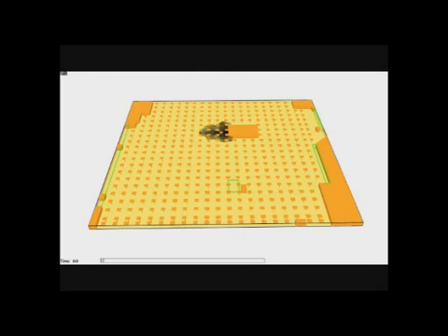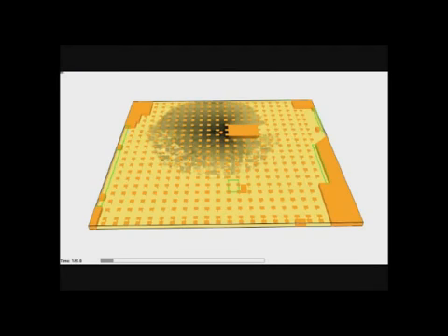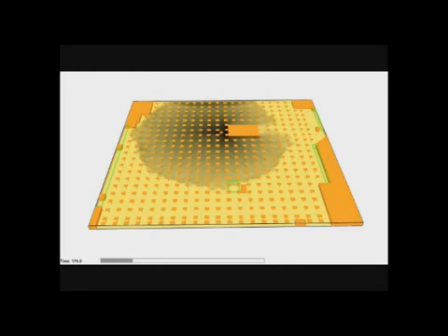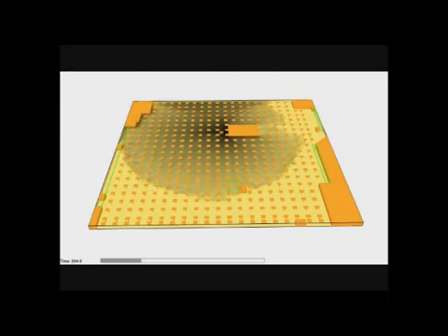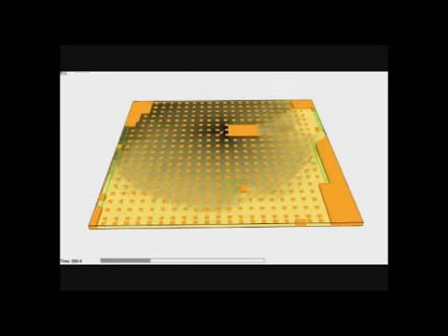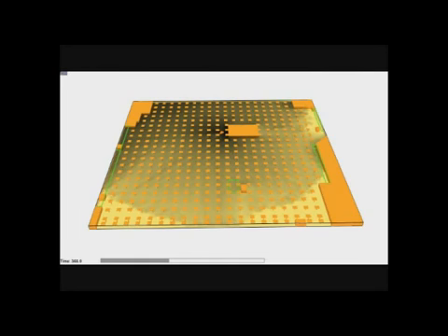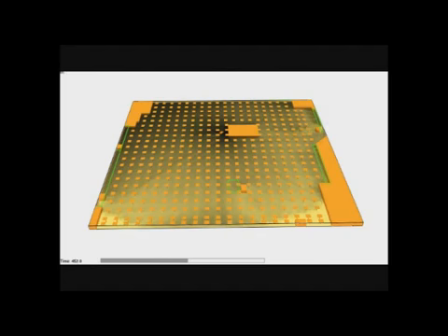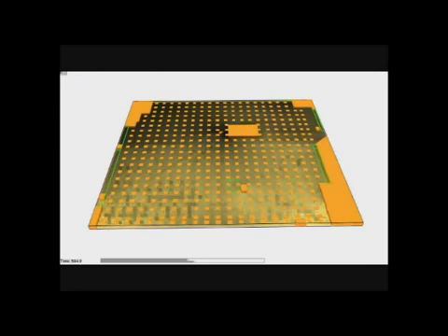In this simulation, you can see how the smoke is spreading in the complete basement. Although visibility is maintained here, in about 200-300 seconds the complete area is filled with smoke. I think this can be very well directed to constrain in a particular zone using mechanical ventilation. We can keep that in a particular zone. We are right now working on designing the system so that we can keep it in a particular direction using just natural ventilation and jet fans.